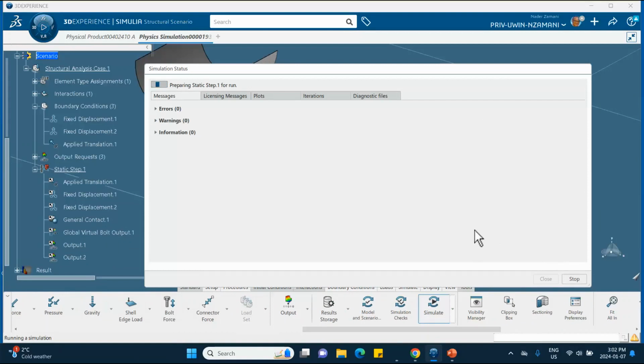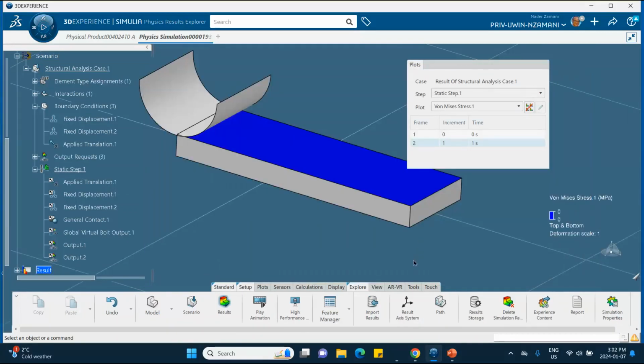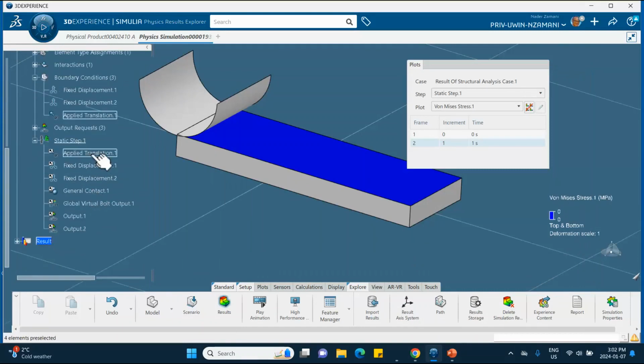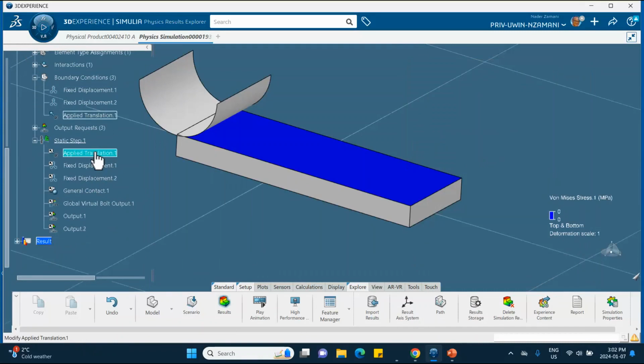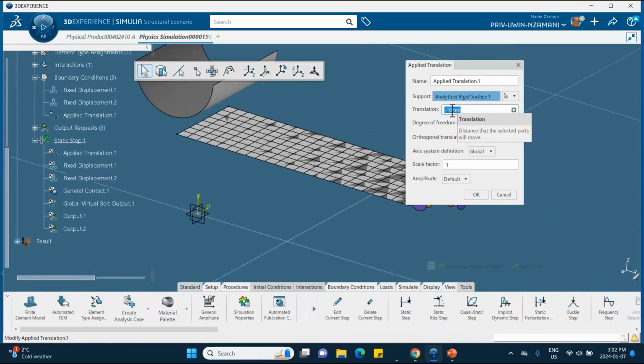So you can see why that thing is so important, because the contact requires knowing where this shell element is, where the top and the bottom surfaces of it are. Should have zero, should have no stresses. There we are. But if we go back here, make it 10.1, minus 10.1, you will see that there will be stresses.